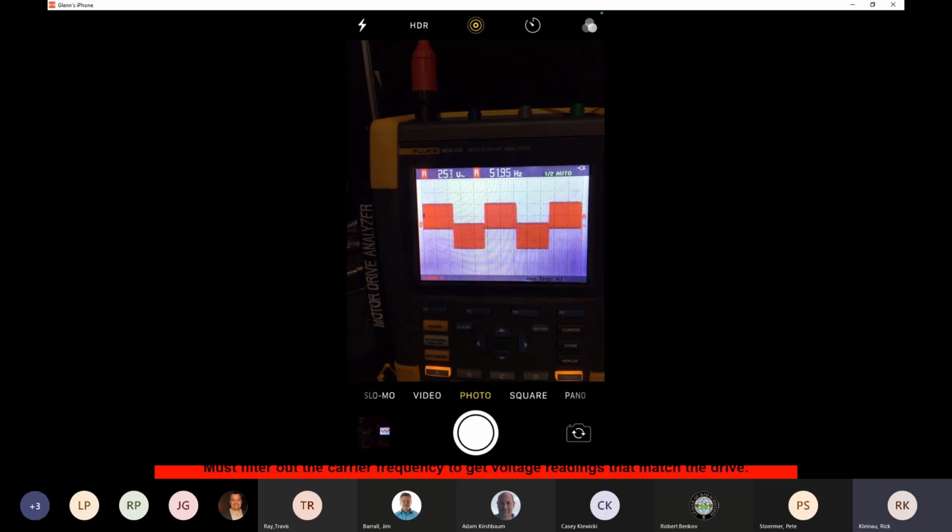You'll see voltage and hertz at the top changing. That waveform stretches out, right? I've got the frequency so low now that the scope meter doesn't know what to make of this. It doesn't know how to calculate readings. It sees a string of positive pulses, then they go negative, and then a string of positive pulses. It can't calculate this. There's no repetitive cycles there on the screen, so it's not real sure what to do.